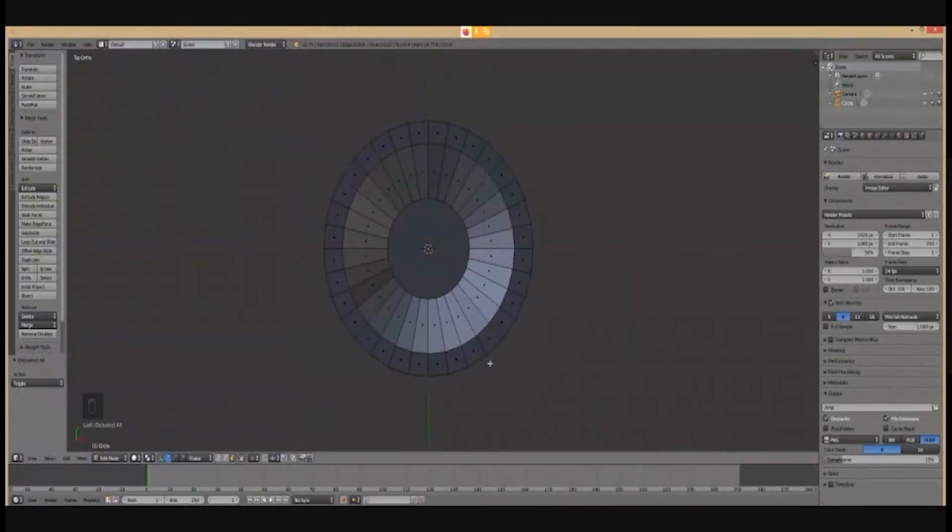Now you can ask me, well, I want to make my handle here, right? Why can't I make it? I mean, it doesn't matter. Even if I make it here, you can rotate the entire cup and the handle will come here anyways. The reason why I'm choosing an axis is because while extruding, I can make sure that the extrusion only happens along that axis, and therefore the extrusion is smooth.